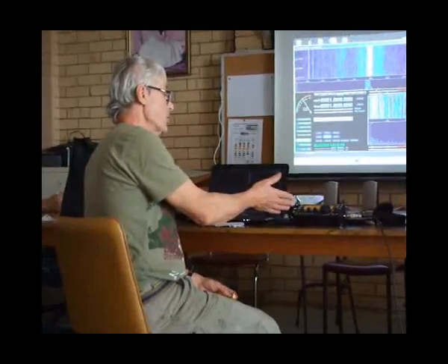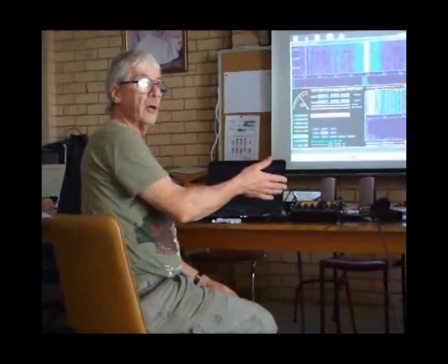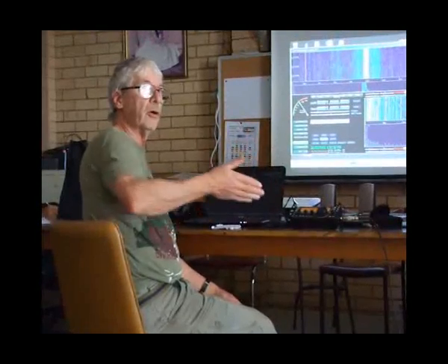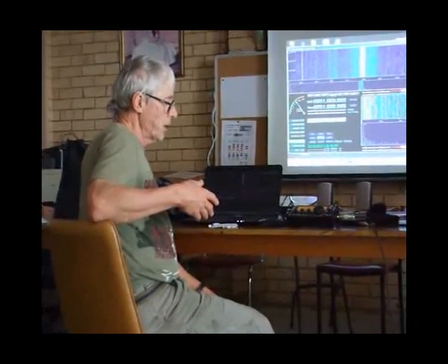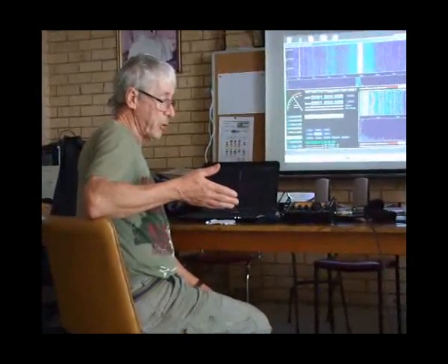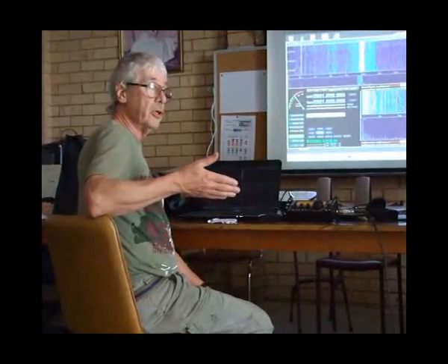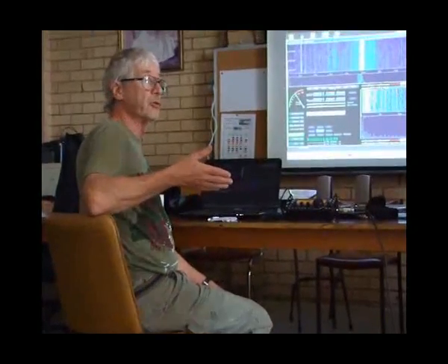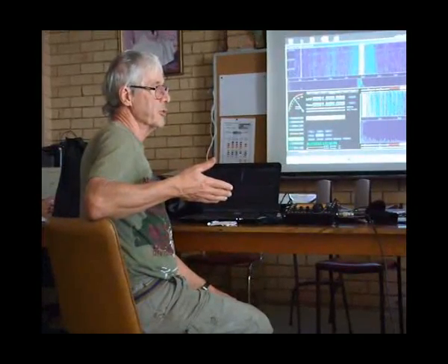Another thing is that the fact that it's a software-defined radio that doesn't have all those normal analog and IF stages means that there's very low phase noise, and generally the internal noise background of the rig is extremely low, so that you can hear incredibly weak signals.